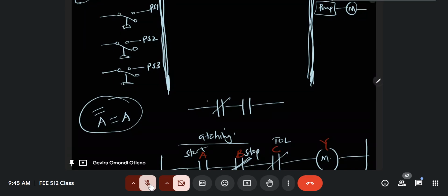if you're having A, you have an A that is negated there. And the value that you find here is based on whether you activate this guy or not. Okay? If you activate this guy, then you simply get that your A there. So you see you've negated. You've achieved the negation. That's why I was drawing this as green. I put the normally closed contact, but I draw this as green, meaning it is already activated. So you have A, you negate it as A complement, but then you activate this device so that it is transferred to the output as A complement.